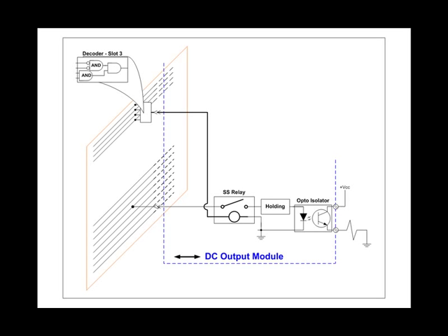So, in the case of the outputs, the data or states, which are stored in memory as a result of the logic, are placed on the backplane by the processor before the slot is activated. The states are felt at every connector on the backplane, but without any of the I/O modules activated, it goes no further than the backplane side of the solid-state relays in each card.